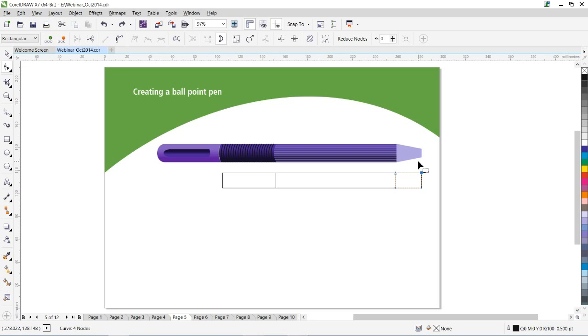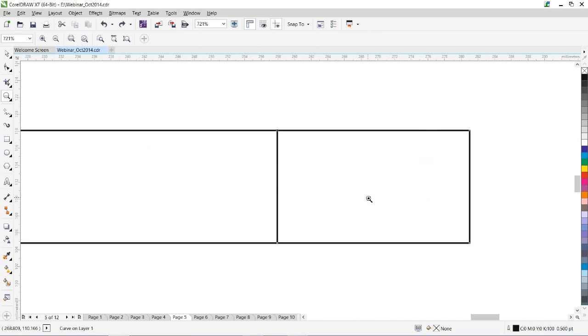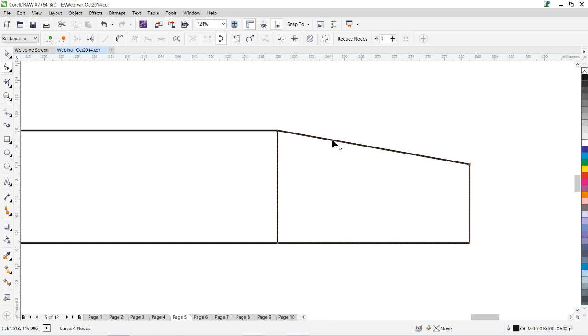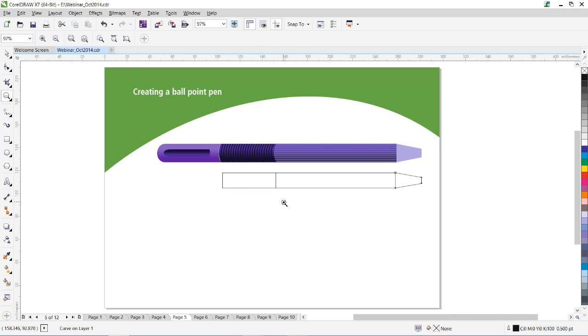Now, modifier keys are Control, Shift or Alt, or the combinations thereof. So if the nudge is set for 2 mm, I can move this node or the object by Shift-clicking the down arrow key, double the size which I have set. It has moved 4 mm now. Same thing here, I select the node, Shift-click the up arrow and it is shifted by 4 mm. So double the movement with the Shift key and half of the nudge set movement with the Control key.